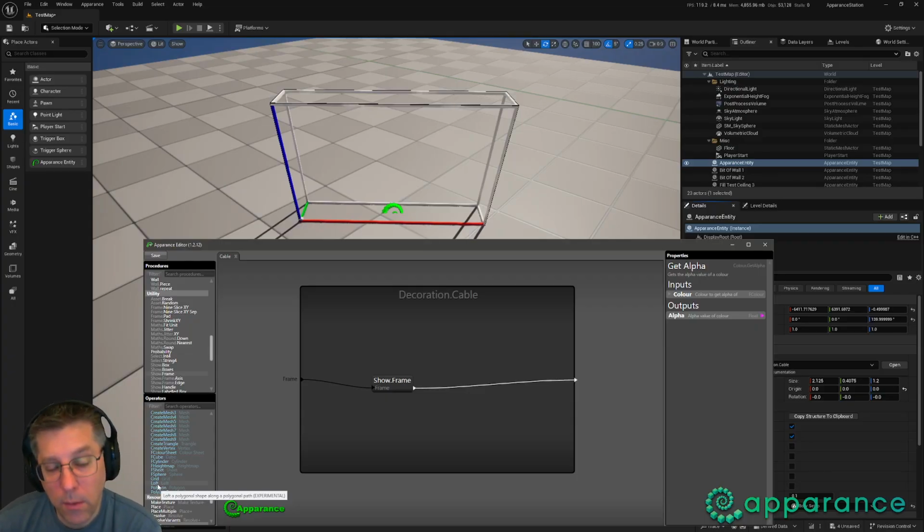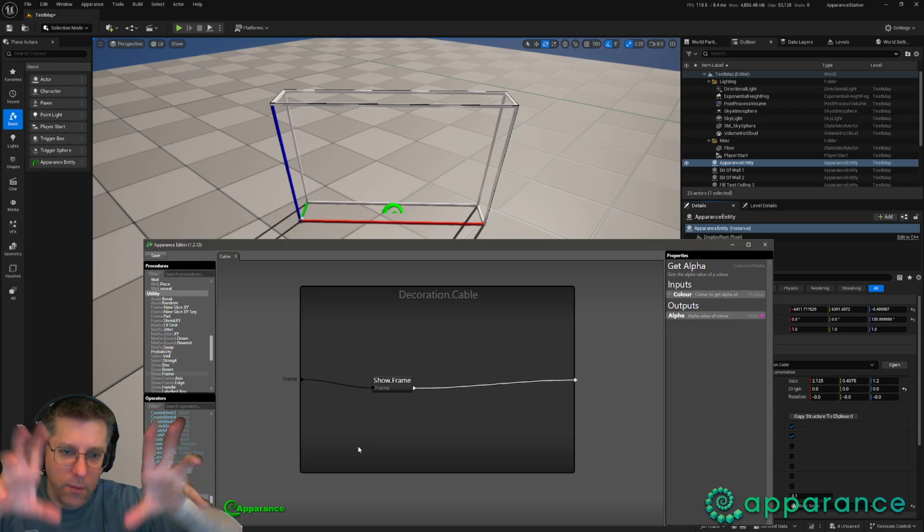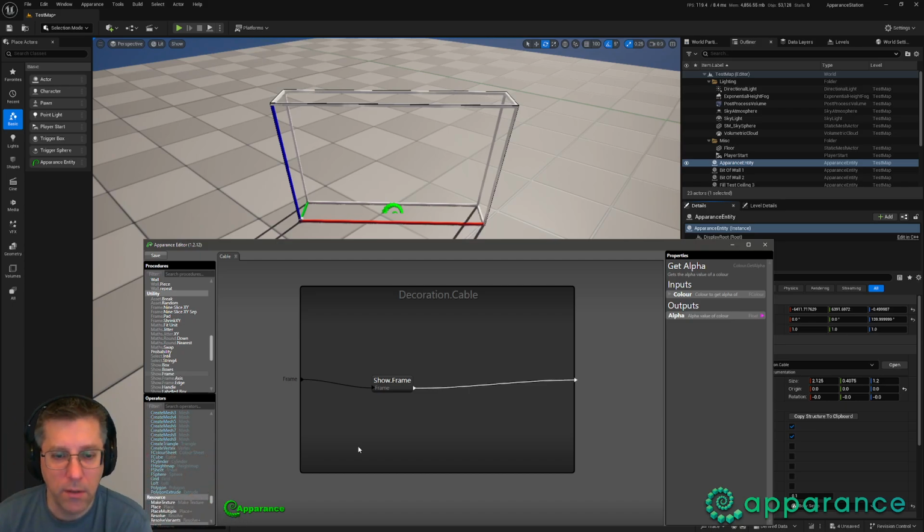There are a few things I'll need to bear in mind with all of this. All the shape stuff works in the XY only. It just ignores the Z largely. There are some cases where it doesn't. But I think the loft uses 3D. Was it in 3D? I can't remember exactly. But most of this, the shape stuff is flat, and you build it flat, you extrude it flat, and then you have to reorient it and position it into the space that you're actually ending up in.